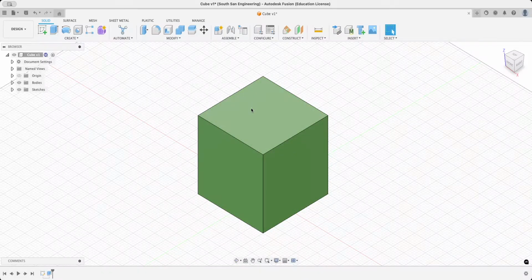Okay, so I changed this cube that I already saved, right? So see up here, there's the little star next to the name. The star means it's not saved. So I need to go save this. So I'm going to click save again. But this time, it's not asking me to name it. It's saying version description. The version description tells you what changes you made between designs. You always put something in the version description to talk to yourself to know what you changed. So I'm going to say I changed the color to green, right? That's my version description. That's literally all you need. You're just talking to yourself in the future, letting you know what changes you made for this version.